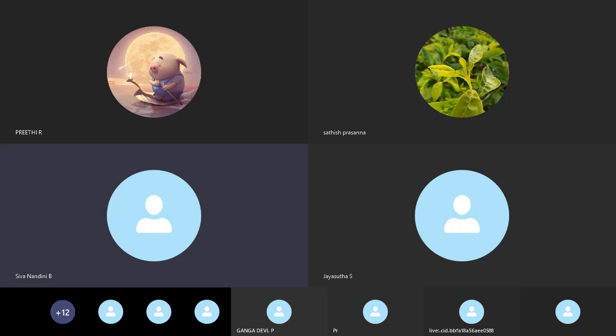In that we also have some letters, that is Z, U, O, I, B. All those letters represent the direction of the pin. For example, B represents that the pin is bidirectional, O represents an output pin, I represents an input pin, and U represents a unidirectional pin.